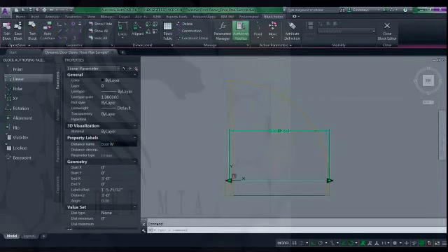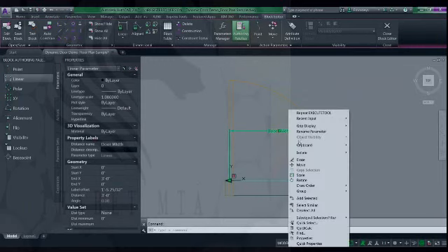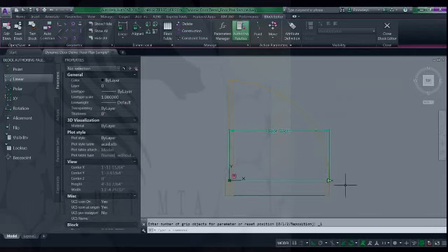And I'm going to name mine for this parameter door width. Enter, and you can see that it changed. And I'm also going to go ahead and right click. And I only want one grip display for this door, and that's going to leave the impact zone right here by my door jamb. So I set my parameter, and then now I need to add some actions.